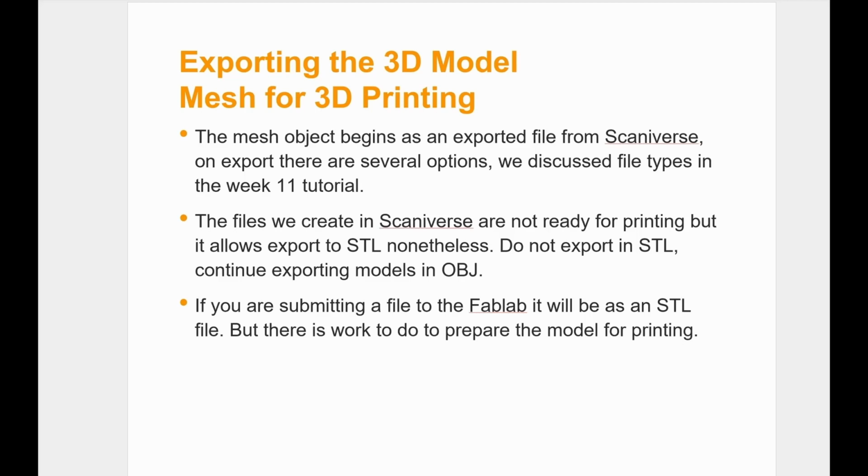The files we create in Scaniverse are not ready for printing, though. So although it allows us to export as STL, do not export it as STL. We will continue exporting models in OBJ. So if you are working from your OBJ models that you previously created, continue using those.